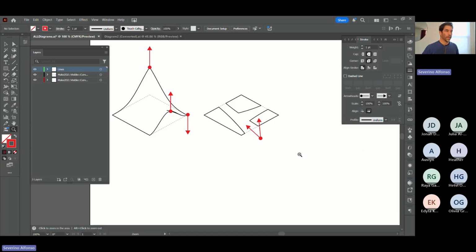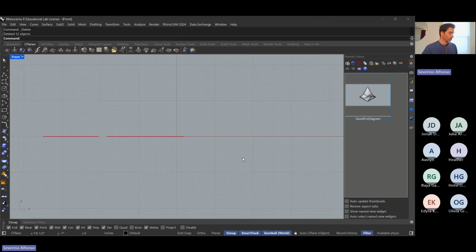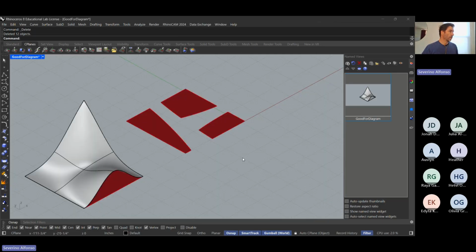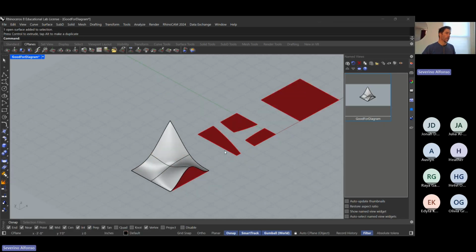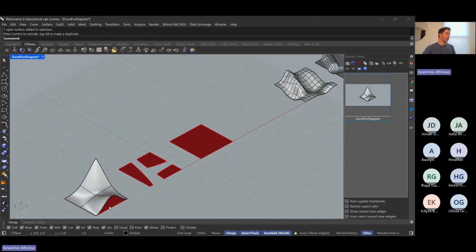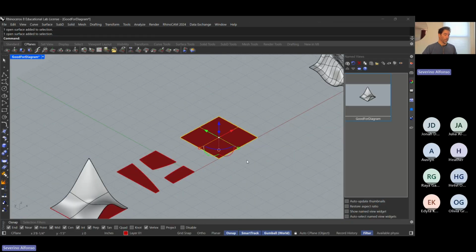let's go back to Rhino. I'm going to delete the make 2D material. Go Control Tab to the perspective, just to have a reference of size. Because I don't know the scale of things, but I want them to be the same size. So I copy this plane there. And I need a cube. You can just do a box command and do this, click, and then click again outside on the right button.